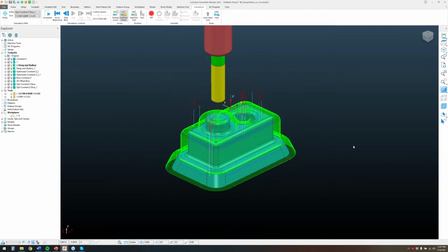Also with 3D offset, always remember areas that are not perfectly flat, near horizontal surfaces sometimes works. It also sometimes works with square pockets with the fillets, but it is best for the near horizontal surfaces that are not perfectly flat. You can tackle completely flat surfaces if you have maybe a ball nose.